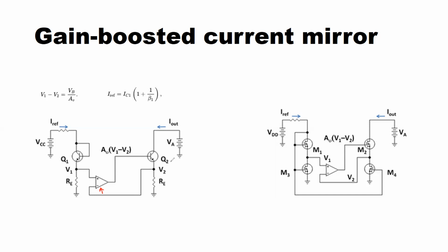So remember, the output transistor, for example Q2 in this circuit, will have this kind of characteristic: the output current I out, which is nothing but the current flowing through transistor Q2, and the output voltage, which is the compliance voltage here, the minimum voltage that we must maintain across this transistor for this circuit to work as a current mirror.